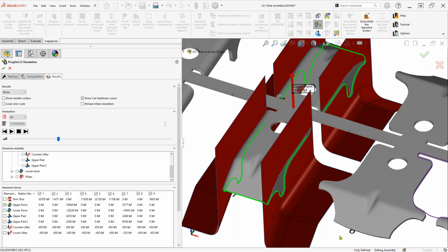And so this was, the initial blank on this was done that way, Brad. We use what we call the LogoPress blank portion or the LogoPress flatten portion, the FEA one-step software for determining this blank, and that's what we fed into it and built the strip around. And that's where you saw it was still relatively accurate on this part. You saw how big the slivers were, how big the areas were, I guess it didn't show you where it added on, but you saw where the leftover material was. But on some parts, you start to get more complex parts, and it can be incredible how much time it saves going in and out of the press. Yeah.